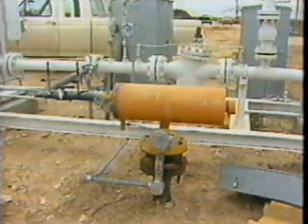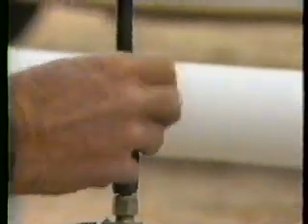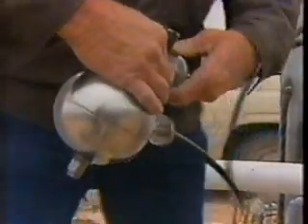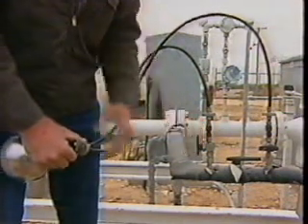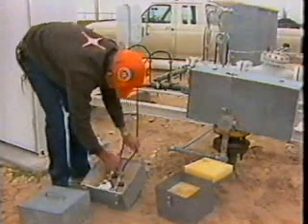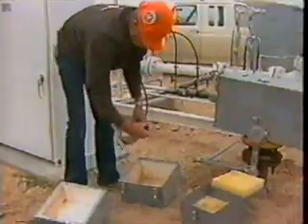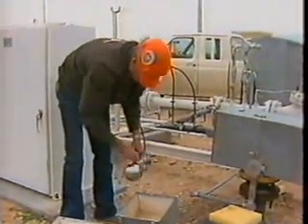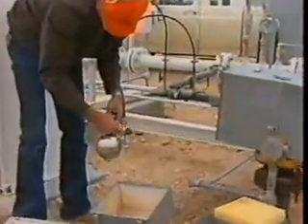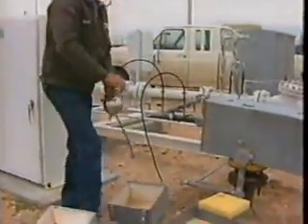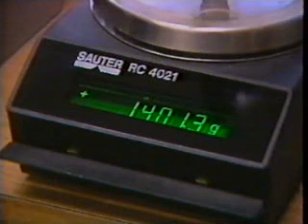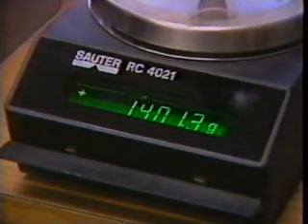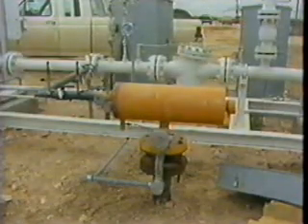The physical proving of the densitometer includes verifying the pycnometer empty weight, purging the connecting lines for the pycnometer, connecting the pycnometer to the flow line, pressurizing the lines and pycnometer to stabilize temperature and pressure in all vessels, insulating the lines and pycnometer, filling the pycnometer, isolating the volume by first closing the downstream valve of the pycnometer and closing the upstream valve, disconnecting and weighing the pycnometer as quickly as possible, establishing repeatability by repeating the steps until two samples give weights within 0.05% of each other. Steps for calibrating the densitometer are in your manual.